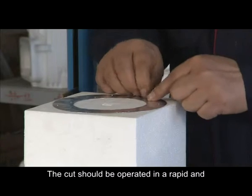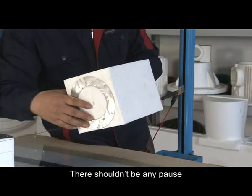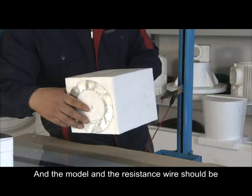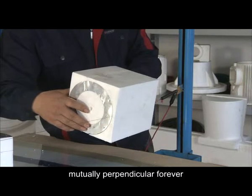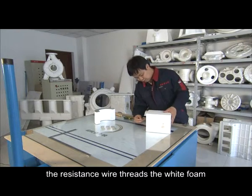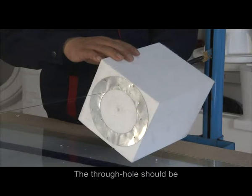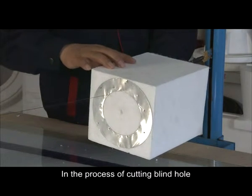The cut should be operated at a rapid and constant speed in one go. There shouldn't be any pause, and the model and the resistance wire should be mutually perpendicular throughout. In the process of cutting a through hole, the resistance wire threads the white foam adjoining the model. The through hole should be controlled within 20 mm.